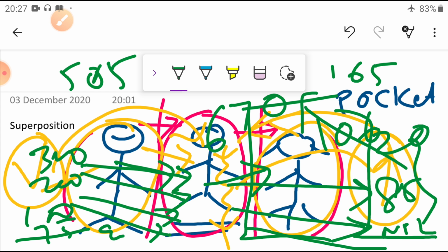After knowing this, once again recover the circuit. Then remove the voltage source, and in its place connect its internal resistance. Then apply the current source. Now find the value in the specified element that you calculated previously with the voltage source, to see the impact of this current source separately.